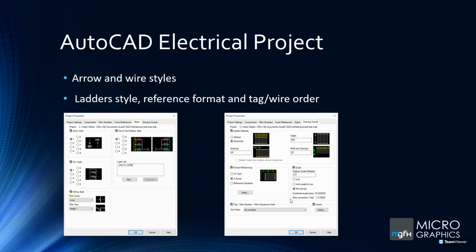This is quite nice because in normal AutoCAD, if you have 2 lines crossing each other and you want that loop going across, you'd draw 2 lines that cross, then draw a circle and trim off what you don't need, and then you get that little loop. Whereas in AutoCAD Electrical, it understands that 2 wires need to cross because we're working with wires, and it automatically puts that loop across. And when 2 wires come in at 90 degrees to each other, how do we do it? A wire T, or a little dot as well. So we've got some variety there.